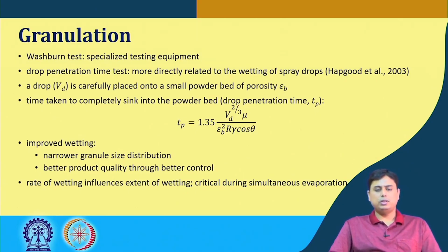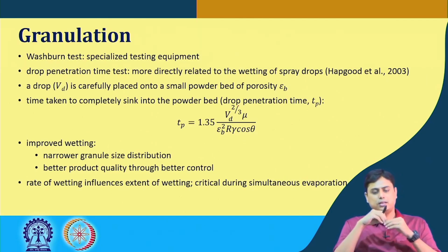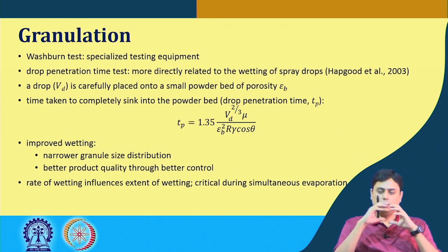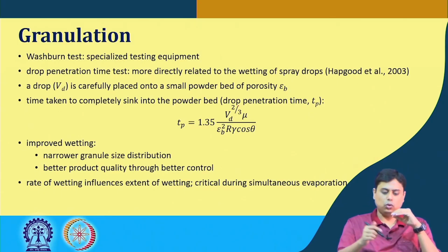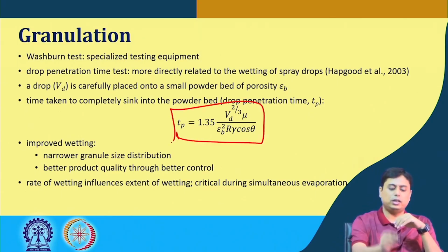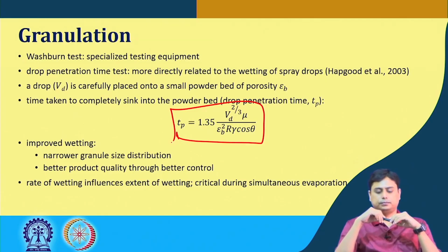So, here what happens is a drop of known volume is placed onto the surface of a bed of the original particles of known porosity or voidage, and then the time taken to completely sink or absorb this droplet into this bed is measured, and that has been shown as a relation of this expression, where Tp is the drop penetration time.